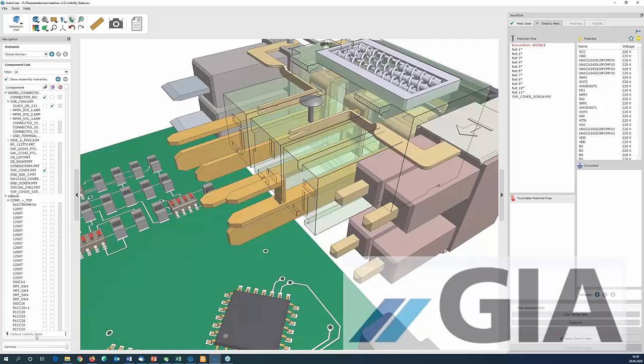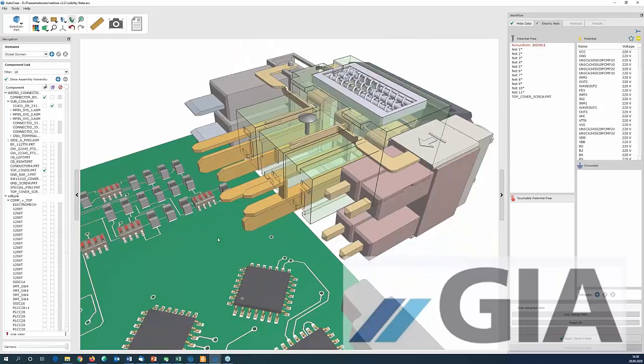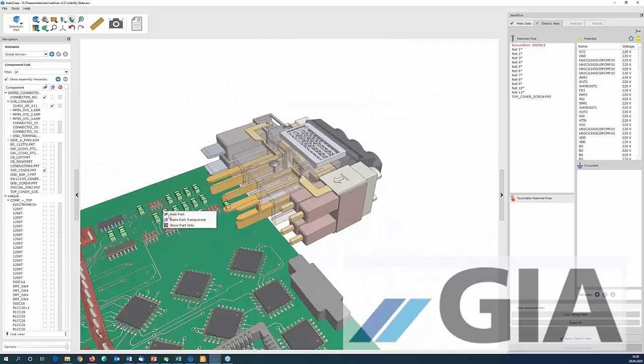It was red before, now it's gray, and now I have the possibility to save the current state as a new state. I can call this my nice view, and now the nice view is active. When I change this view by hiding some more things, the view is again with a gray color indicating that it's not active anymore, but I can anytime reapply this nice view.